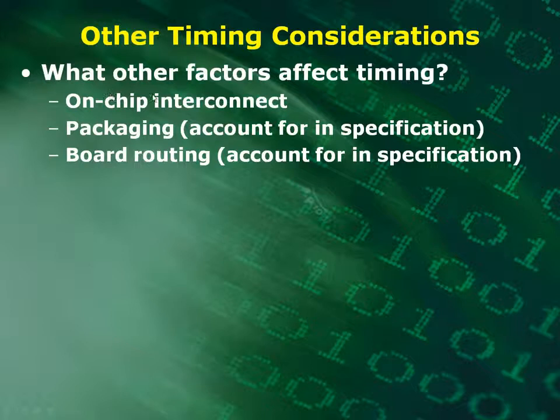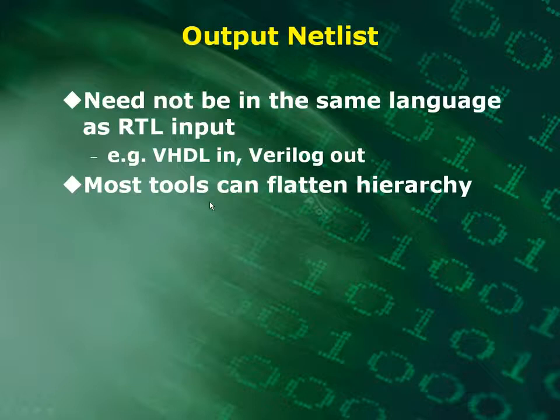And these are some other factors that can affect timing too. Output net lists. They don't have to be in the same language as the RTL input. It could be in VHDL or Verilog or another format. And most tools can flatten the hierarchy.